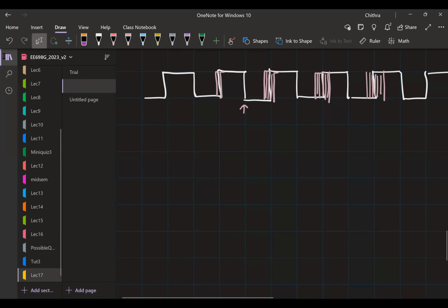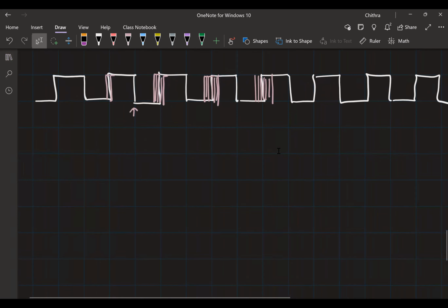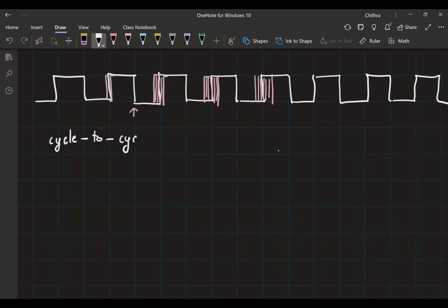Yeah, so because absolute jitter is unbounded, we tend to quote cycle-to-cycle jitter for a standalone oscillator. Because if I take two adjacent periods, we don't expect the period to vary by a large quantity. Now that said, depending on the application, you may want to look at n-period jitter and other forms of jitter.